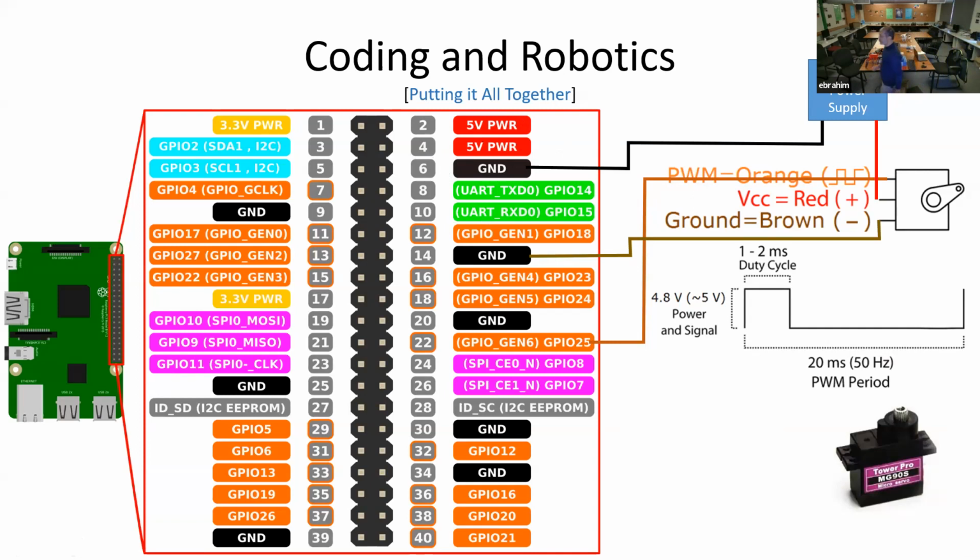Okay. So the question is, can we plug or connect the servo motor to the 5 volts? Can we connect it? The answer is maybe. Why do we think maybe? Because we need to look at the current requirement, because these servo motors draw quite a bit of current.